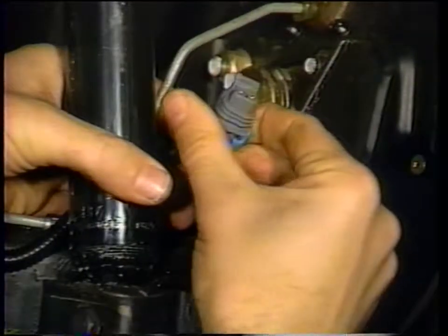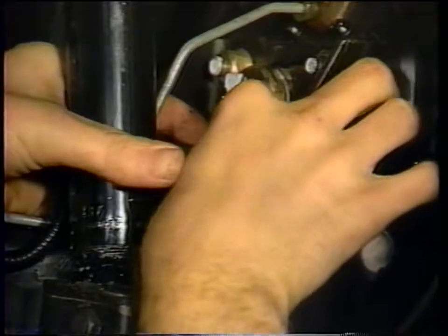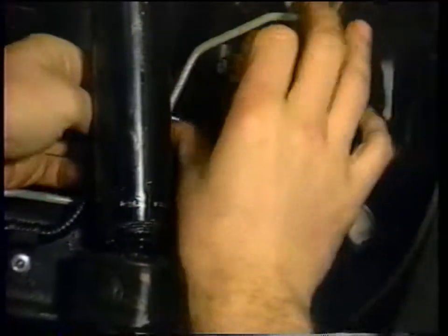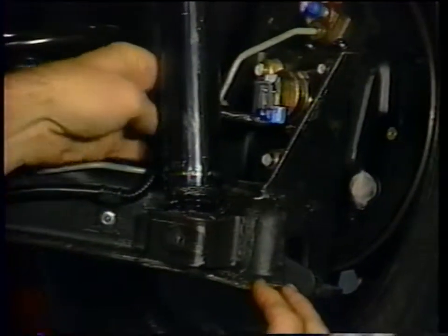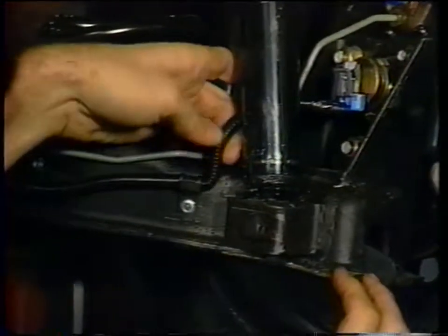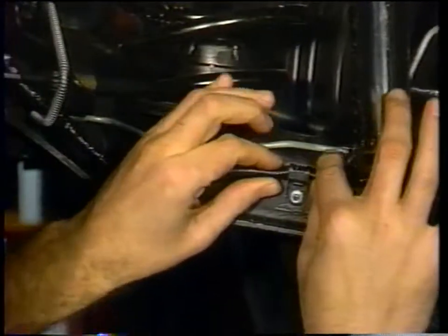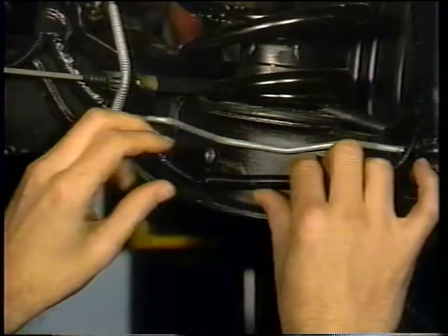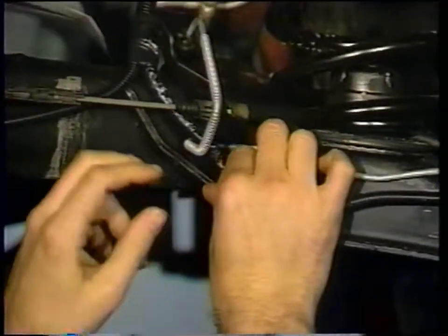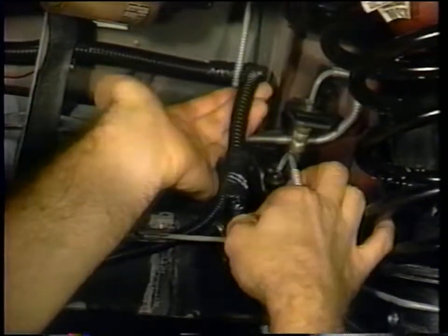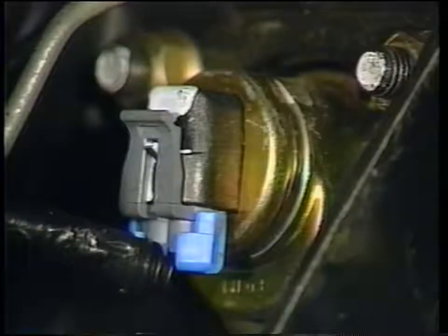The wheel sensors are connected to the main wiring harness by a jumper harness made of highly flexible twisted pair wiring. The wires are twisted to reduce radio interference. Their flexibility also allows them to handle the motions of the suspension. If the sensor wires are broken, loose, or damaged, replace them rather than trying to repair them. Soldering, splicing, or taping can come loose as the wires flex with the suspension.